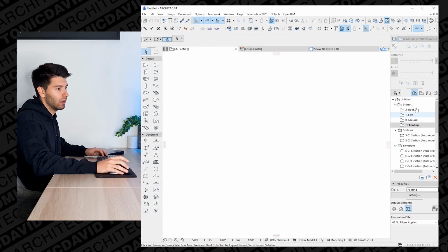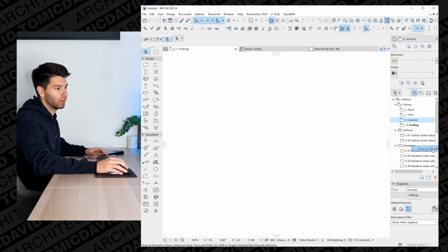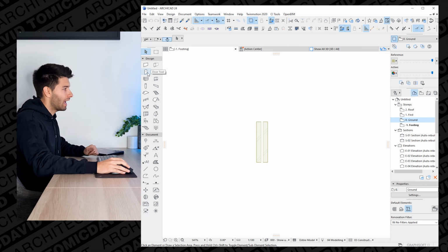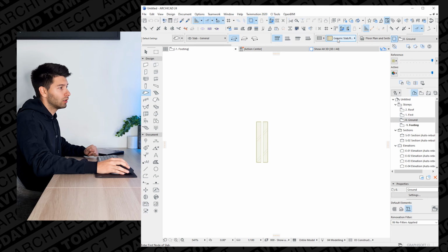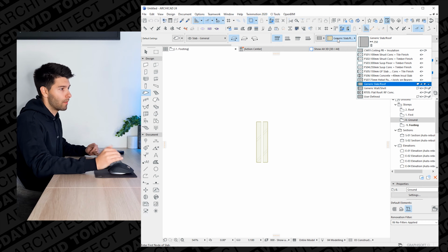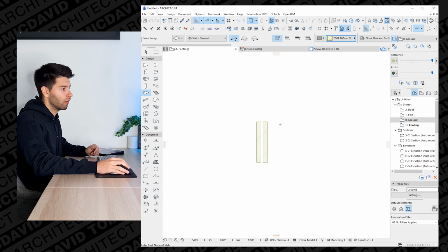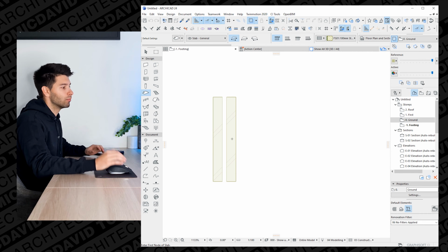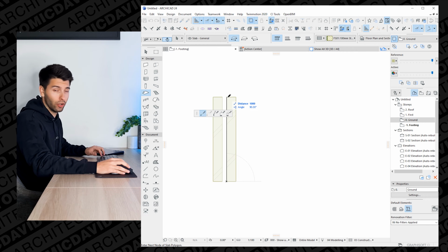Moving underneath, we'll scroll across to our right panel over here, right clicking ground floor plan, going show as trace. And then what I'm simply going to do is come across to the slab tool and select a different type of slab. Now let's go simply with a 100mm concrete slab with a tile finish. Because this is brick, we are going to stop the slab right here on the internal leaf.